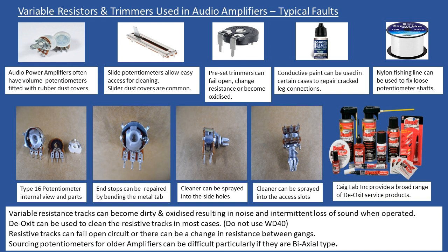And normally you're going to do this without any speakers connected, but again inside, if it has a headphone jack on it, not the power amps but the hi-fi amps, I just plug in the headphones, stick them on my head of course, and then I can listen for noise. And what you may well find is it tends to be at the extreme ends, so it could be the beginning minimum setting or the max setting, where maybe the volume control hasn't been used extensively, particularly at the high end, or you may just find a dead spot.